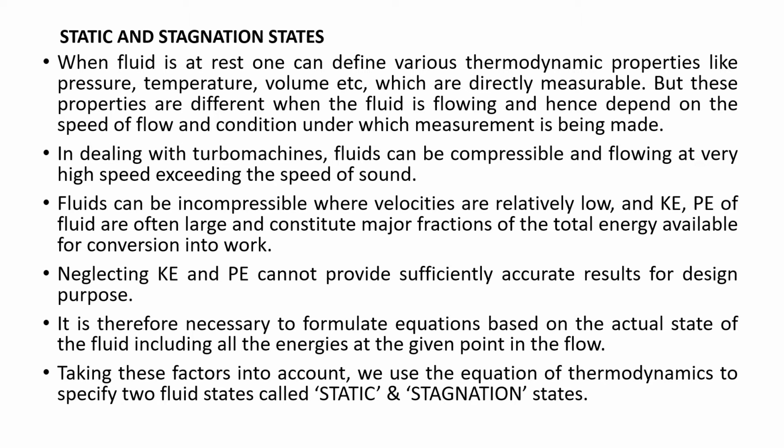Neglecting kinetic and potential energy, they cannot provide sufficiently accurate results for design purposes. It is therefore necessary to formulate equations based on the actual state of fluid, including all the energies at the given point in the flow. Taking these factors into account, we use equations of thermodynamics to specify two fluid states. They are called static and stagnation states.